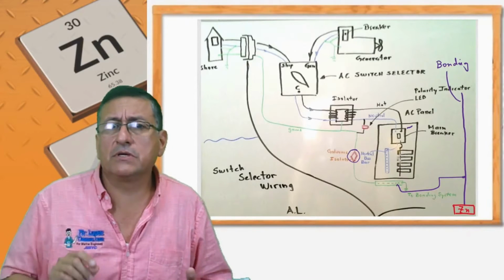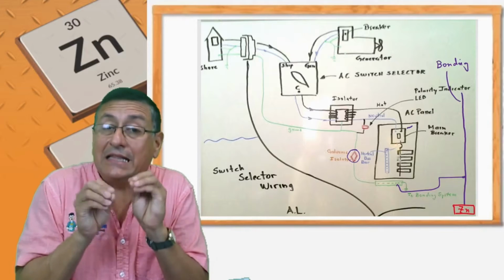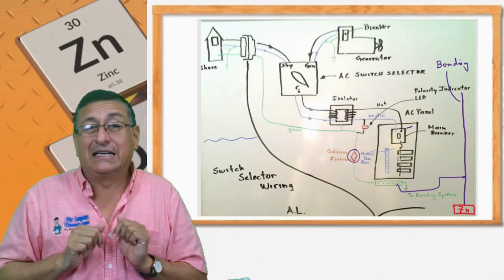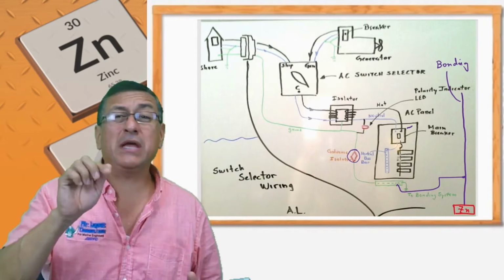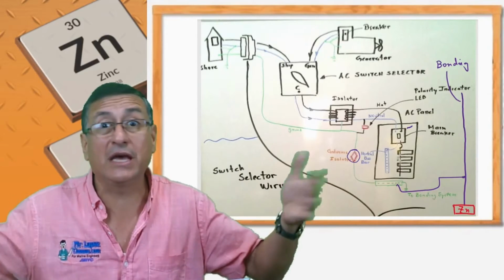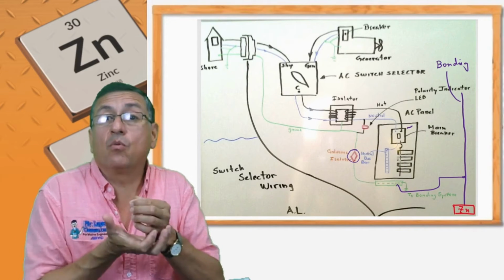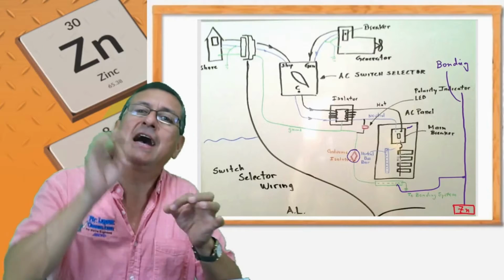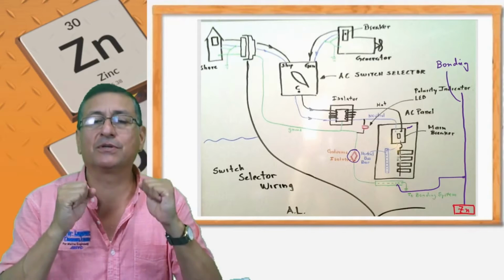But if you have 3 amps, 2 amps constantly, you have a leak, and you need to identify where that leak is. Because that leak of current, at the end of the day, affects all the elements connected to the bonding. Can you imagine all the fittings, all the through holes connected to the bonding, with 3 amps constantly flowing through them for 1 hour, 2 hours, 1 day, 2 days, 1 week? Those through holes, in contact with salt water, produce pitting corrosion, and the pitting corrosion perforates and creates a hole, and your boat sinks. That's the problem. Now we are going to start with that analysis.